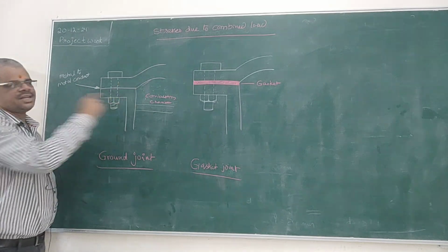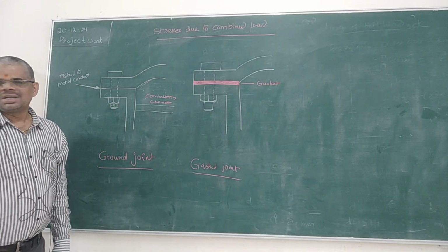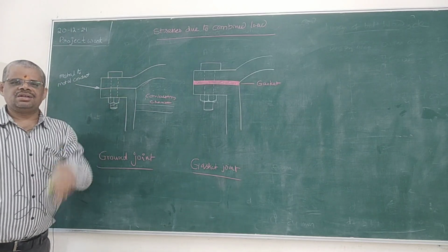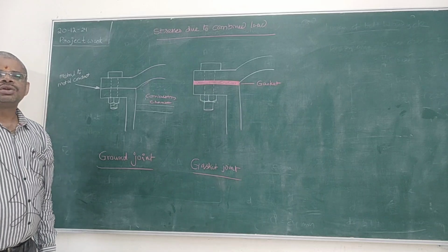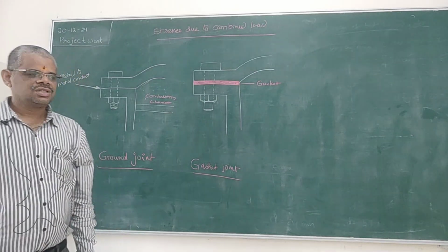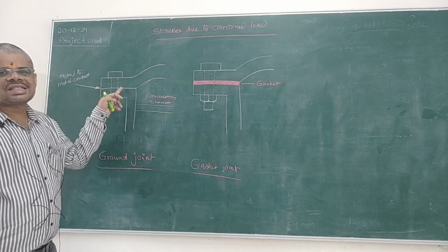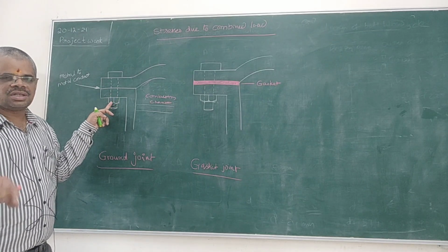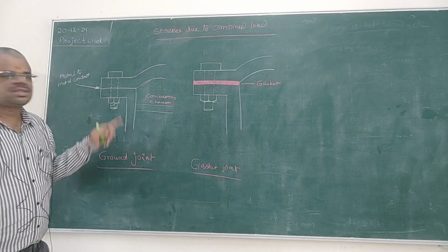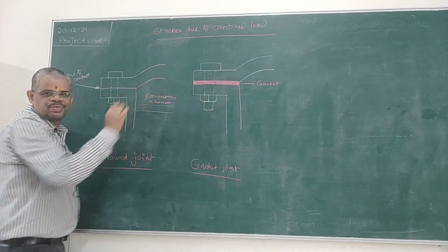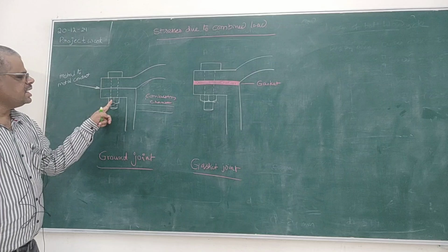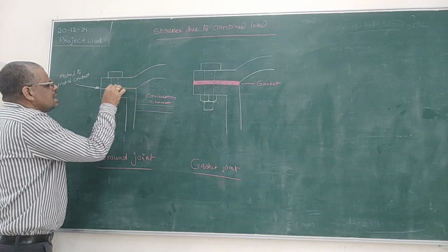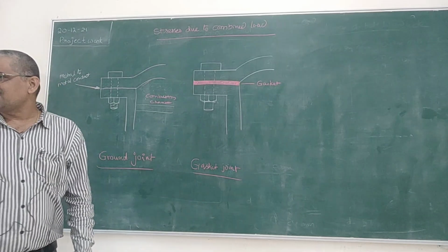As the nut is tightened, there will be some load due to tightening on this bolt, due to which it may fail. That is the initial load due to tightening. So we must use maximum effort to tighten this nut. Why? Because in this place the combustion takes place. If this tightening is not perfect, then these combustion gases may escape through the gap to the outside.